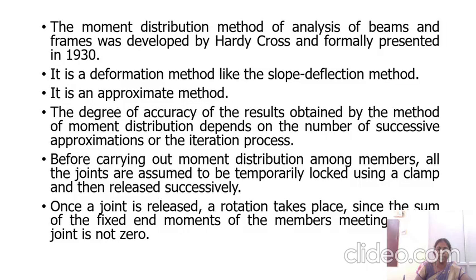In this video lecture, we are going to learn about the moment distribution method. The moment distribution method of analysis of beams was developed by Hardy Cross in the year 1930. It is a deformation method similar to the slope deflection method, and also it is an approximate method because it involves the iteration process. We can't end the process at a particular stage.